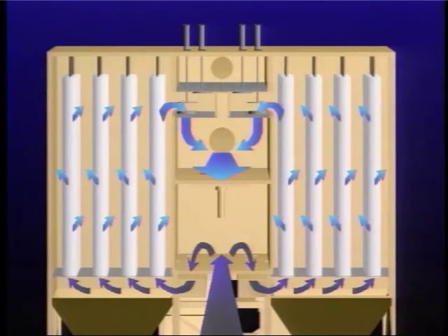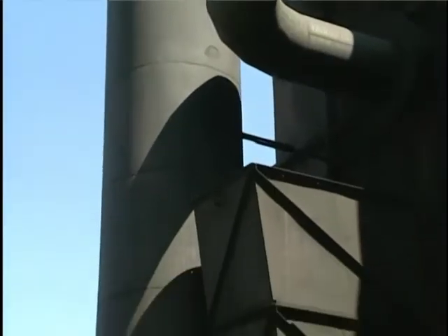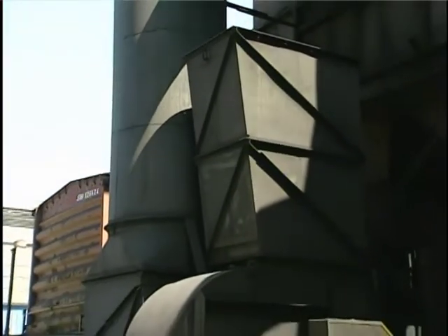Excessive air infiltration, bag blinding, and undercleaning may result in decreased gas flow rate from the source. Fugitive emissions and decreased hood static pressures are also indicators of these problems.